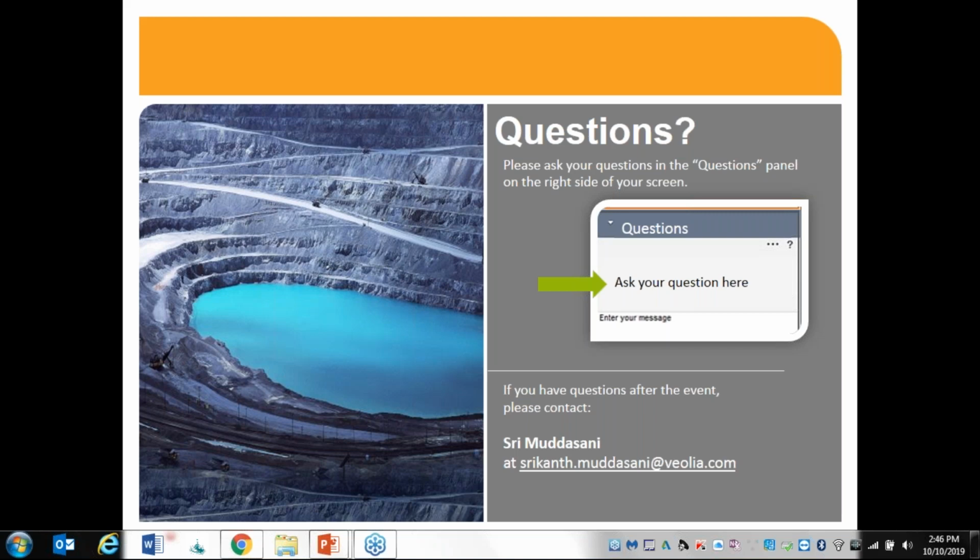The reaction time is based on the application and some other factors. I would suggest with good sludge recirculation, you should run around 30 minutes to 60 minutes. I would suggest running a pilot study or a bench scale study to determine the optimum based on the case scenario. I would suggest around a 30 to 60-minute reaction time.